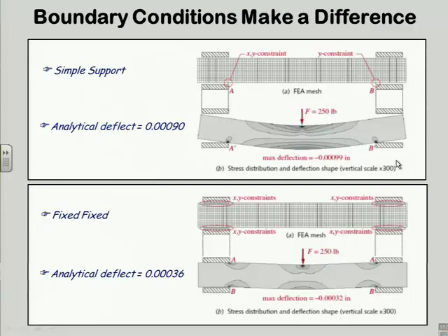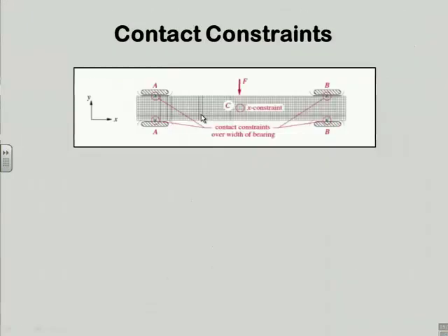I still haven't resolved the issue as to which of these is correct. But notice that it's hard to see, but I show a little bit of white space in there. Because in this particular case, the deflection was not sufficient to cause this to curl up so far that it hits the other side of the bearing on the top. And if it does, that's going to change things very dramatically, right? Because now I'm switching from a simple support to a fixed type support. But I've already baked in some slope. So it's not like it started out fixed.